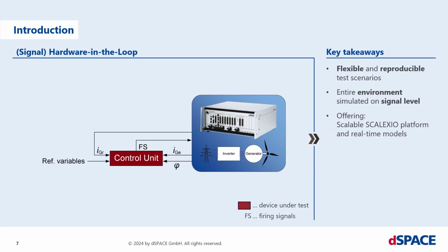And dSPACE has an offering of the scalable Scalexio platform. You see here the Scalexio lab box. Scalexio stands more or less for scalable and flexible I/O. You see here the possibility to add many cards. For example, starting with an FPGA card where the real-time model is running. And then you have the possibility to add as many I/O cards as you need for your signal hardware in the loop setup.